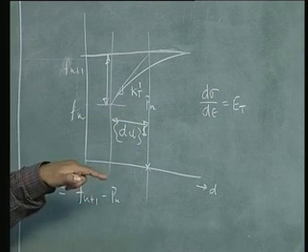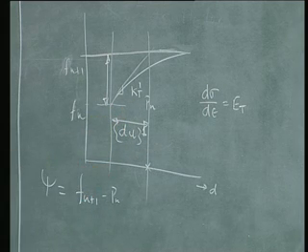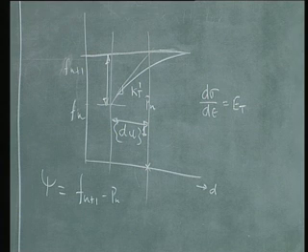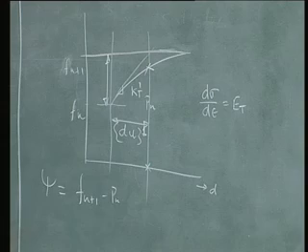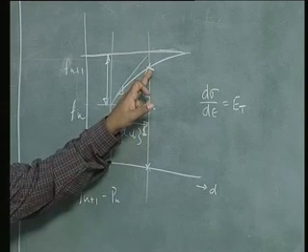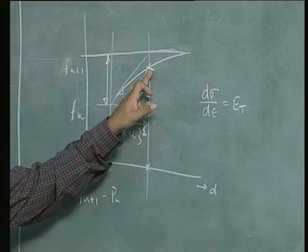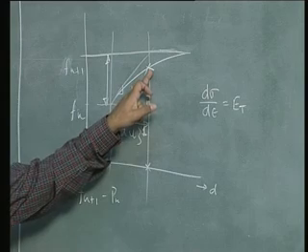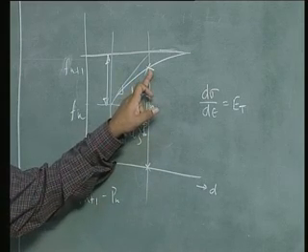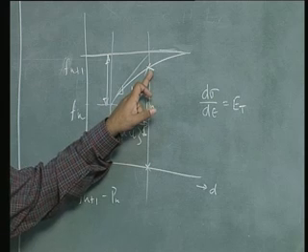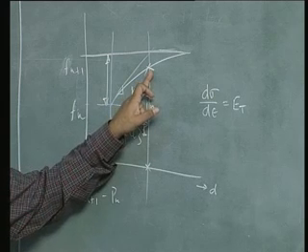Knowing sigma I can calculate the internal forces, okay. Or in other words, this is the point that is given for this displacement, the force, the internal force is given by the point lying in the load deflection curve. So, if this were to be the deflection, this will be the load, that is what it means. So, this will be my new internal forces.